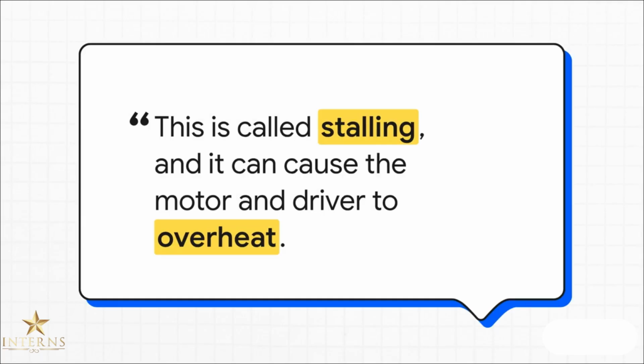And that last point is super critical for safety. If you send too little power, you might hear the motor kind of hum or whine, but it won't actually turn. This is called stalling. It's trying to move, but it can't. And all that electrical energy that's being pumped in has nowhere to go, so it turns into heat. And that heat can seriously damage both your motor and your driver board.